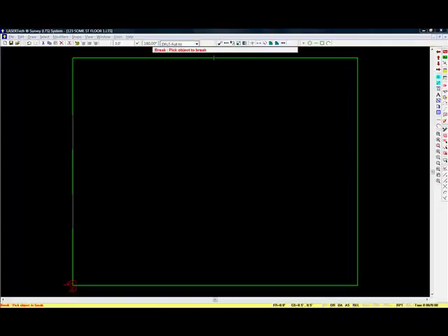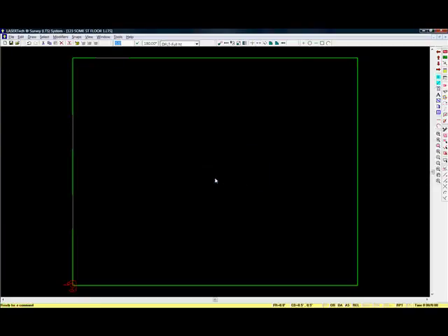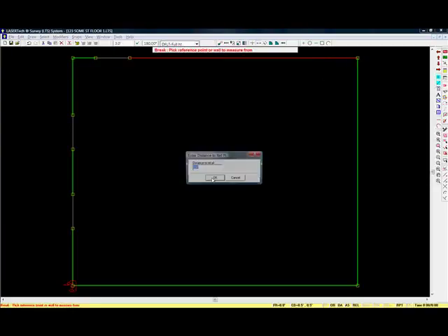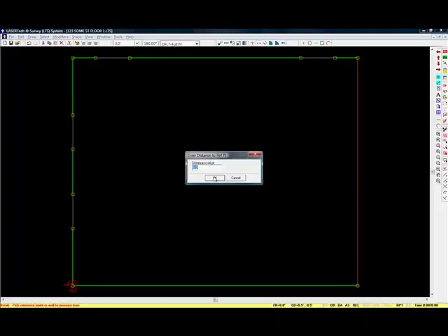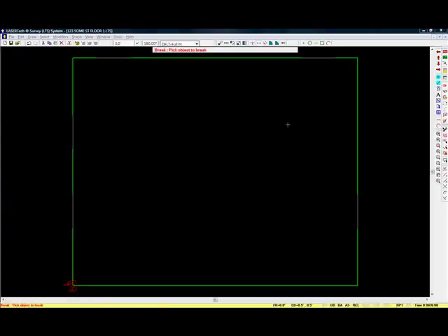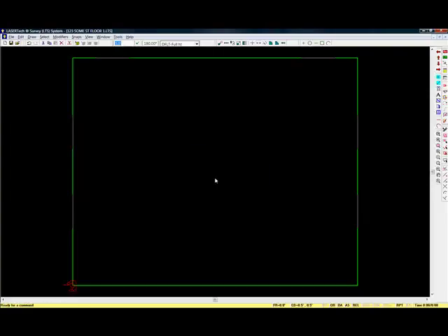And we'll do the same thing again with this wall. We'll come over 2 feet this time, and we'll put a 3-foot opening in. And we'll also measure from this corner 2 feet and a 3-foot opening. And we'll put this door, 2 doors over here. Again, measuring up from this corner, it's 5 feet and it's a 3-foot opening. And one more on this wall. We'll measure down from this corner, 5 feet and a 3-foot opening.